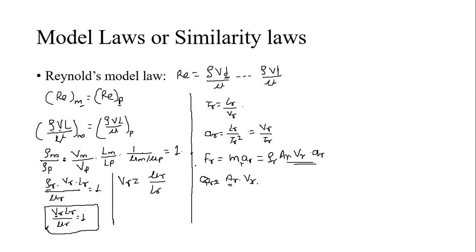In such conditions, for such type of flow phenomena, including the motion of airplanes, flow of incompressible fluid in pipes, motion of submarines which are fully submerged under water, and flow around structures like piers of a bridge, or other bodies that are completely immersed in a moving fluid, for the preparation of the model of such structures, we need to apply the Reynolds model law.